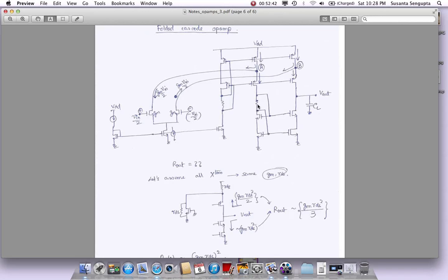All the other nodes, which are low impedance nodes, as we'll look at, they will create low impedance poles, and hopefully they're far away where we can still get a good phase margin. Okay, so that is the other key thing to note here in case of this thing. So let me first explain how this thing works.